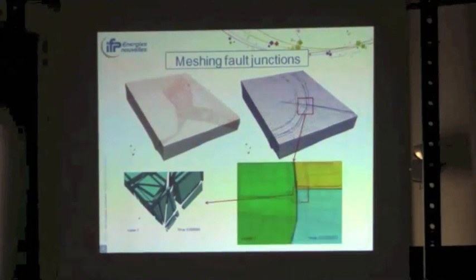They are very stretched, and they ruin the conditioning of the problem, making it impossible for the numerical solver to solve. The meshing tools sometimes fail in generating a mesh in these areas, and when they succeed, the shapes of the elements are very bad.